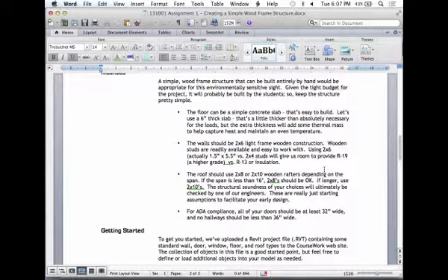It'll do that and kind of tip over. In fact, a lot of buildings fail in earthquakes in that way. So what we do is we put a layer of sheathing, like plywood, on the outside that'll keep it from doing that, keep it from racking. So in the section view, there'll be some sort of layer of plywood. There'll also be some layer of some outside material.